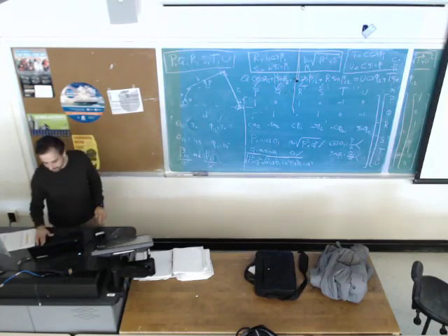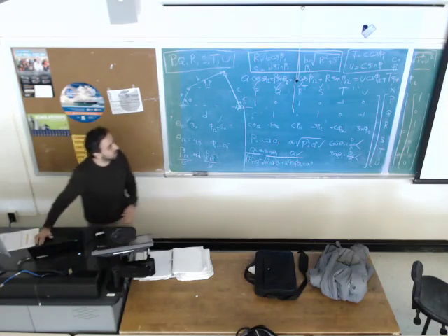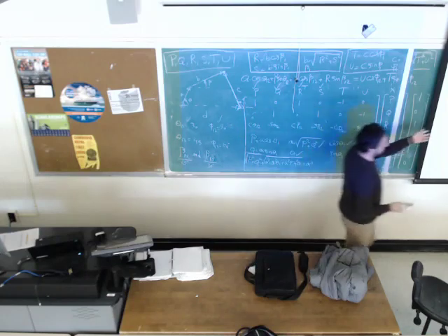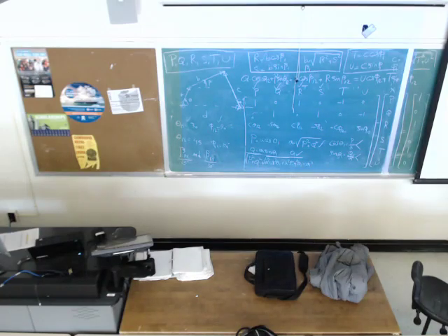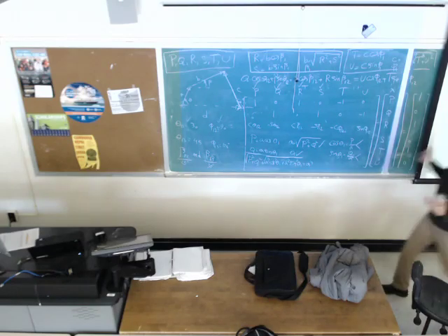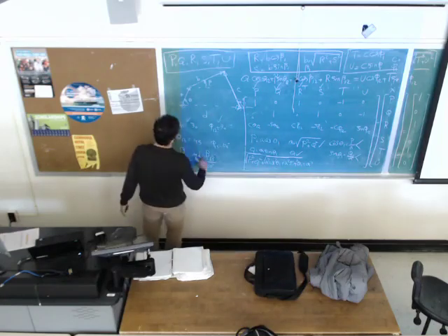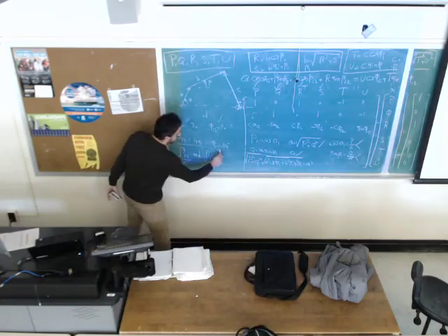You can do it by hand, but it's a lot of calculation. So it's better that you use code or software like MATLAB or Excel to speed up the design iterations. You might be given different types of criteria. I might say I would like to have double rocker or crank rocker, or I would like to have non-Grashof. Then you should satisfy that.